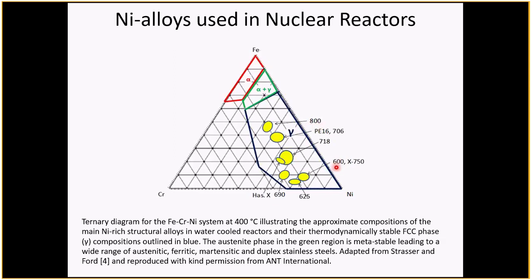But it was primarily used in some of the earlier steam generators in early reactors, but there were some heats of alloy 600 which didn't behave too well, so I think many operators now tend to stay clear of alloy 600. I think alloy 800 is preferred, and alloy 690 are now the preferred steam generator materials. I think alloy 800 is used somewhere else, not quite sure.